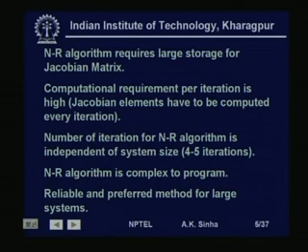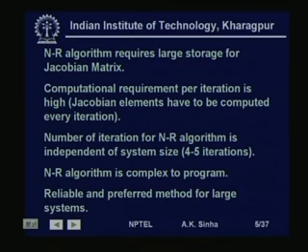The Newton-Raphson algorithm is somewhat complex to program. However, it uses the real and reactive power equations separately, so it deals with real numbers and not complex numbers. That is, all quantities used in the Newton-Raphson method for power flow are real numbers. We do not work with complex numbers in Newton-Raphson power flow.